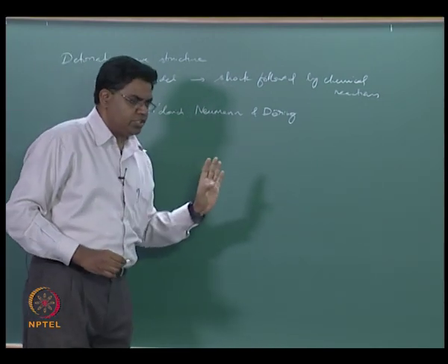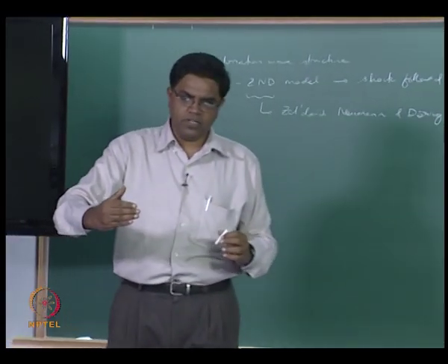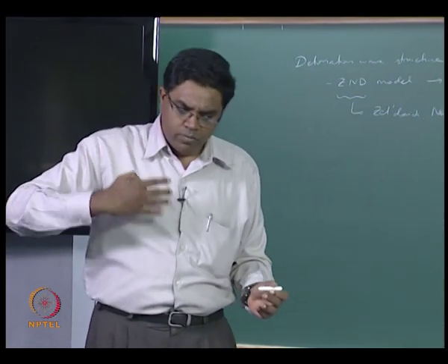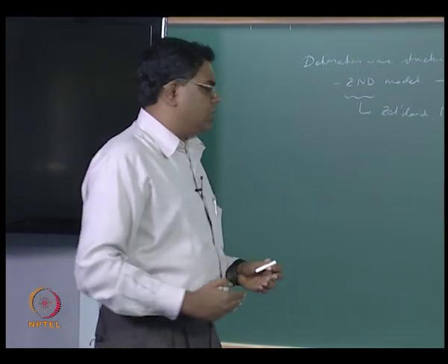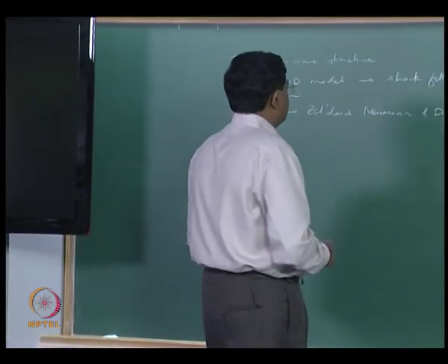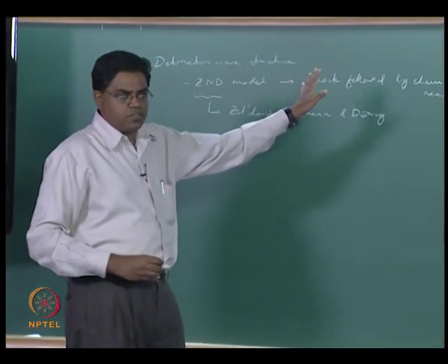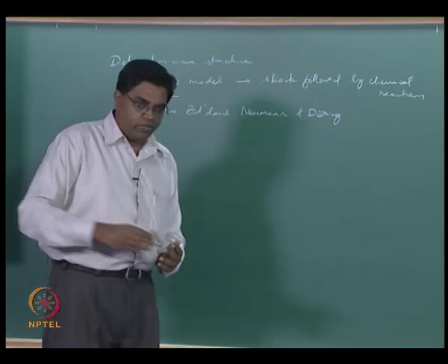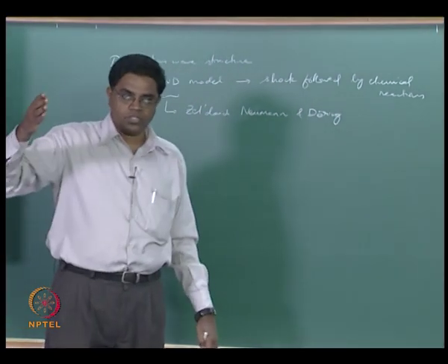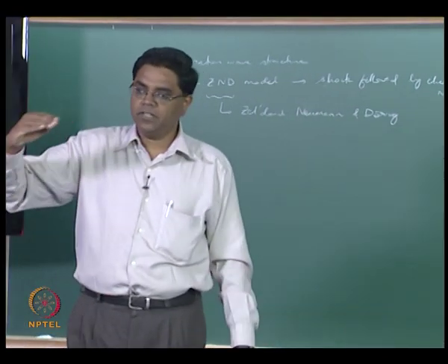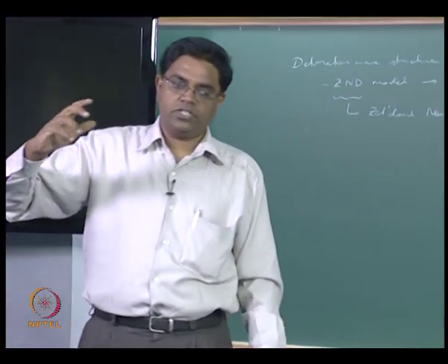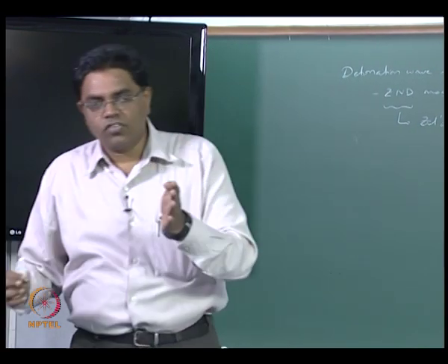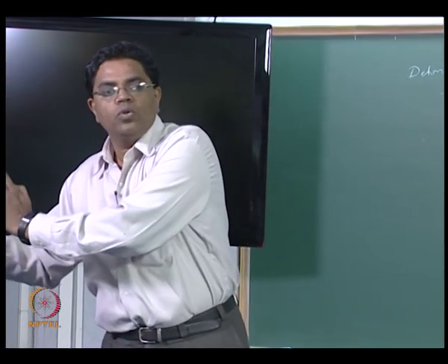So keep in mind, detonation waves propagate at supersonic speeds, so do normal shocks. So we are talking about a normal shock propagation, and the job of the normal shock, as far as the detonation wave is concerned with respect to this model, is to increase the temperature downstream of the shock to a high enough level that will now get the reactions going at as fast rates as is required for the reaction zone to follow the